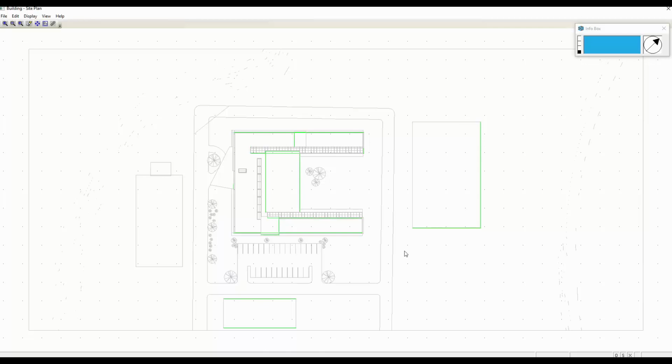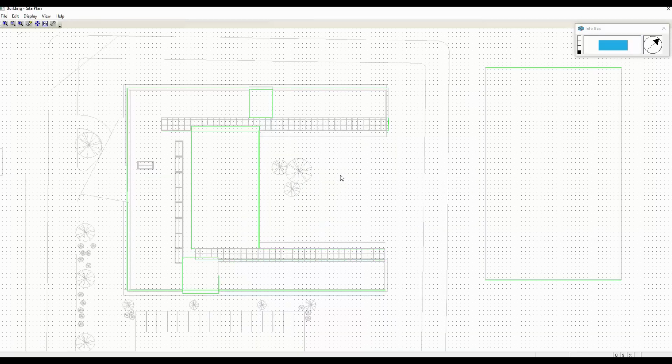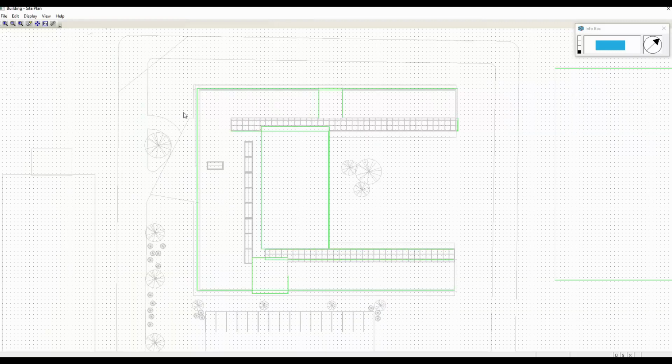So what we would need to do first is to simulate our target building. Highly likely that this is going to cast a shadow on itself. So you would select all the point heights of the target building. So this was built up using the basic C shape on the building. And then we did the atrium area by changing the heights, plus the plant rooms. So to describe this angled atrium area that we looked at on the front in the Revit model, you would then select Edit, Graphically, and you then specify the point height prior to entry.